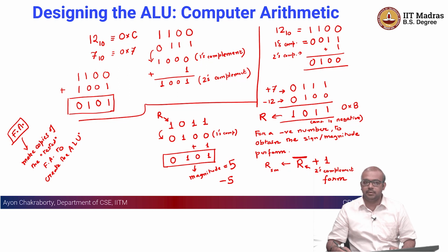There is a module that you need to define for a given component and instantiate that thing, right, instantiate that class as if. It is very much analogous to your object oriented programming, where you have the concept of a class and you create an object, right. So, similarly you can think of this as kind of analogous to that concept, where you can have this full adder class and you instantiate let us say 8 objects of the full adder, and these 8 objects of the full adder are going to instantiate an ALU.